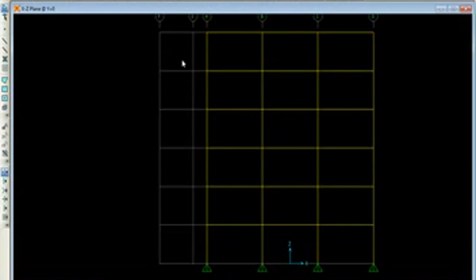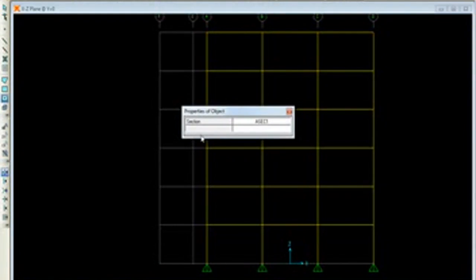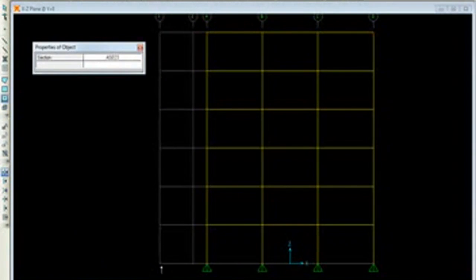Now we can see the things acting over here. So now what you can do is you can assign a shear wall to all these 6 floor members. So I'll go to quick draw area element command, and so put this aside, and now we can just press on the places where the shear wall is being assigned. Okay, and now if you can just go to set select mode,